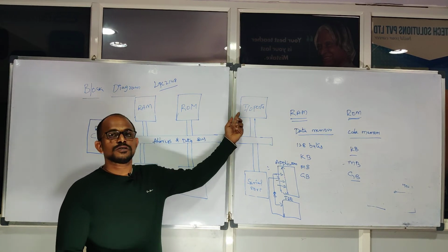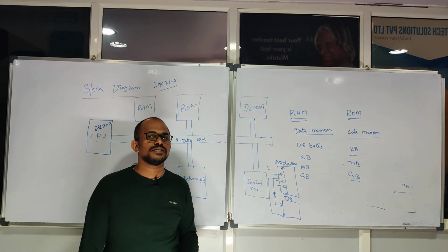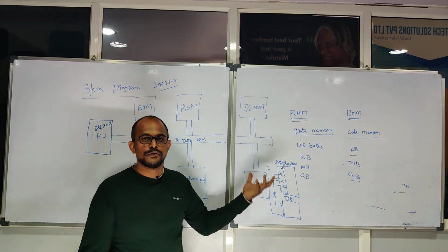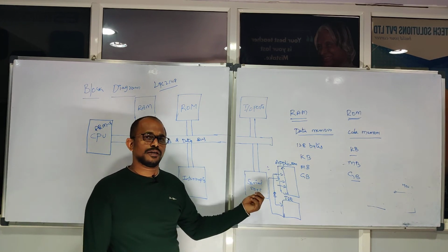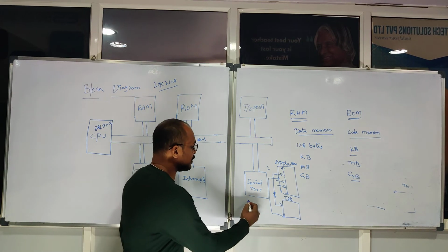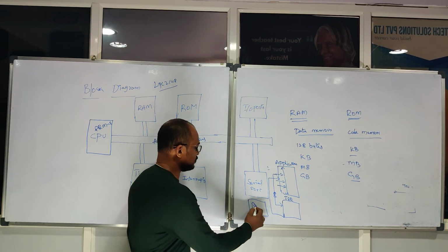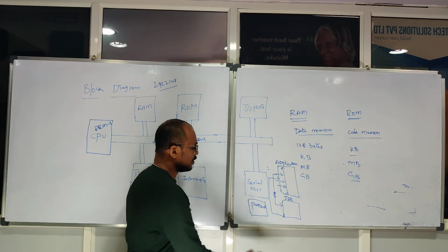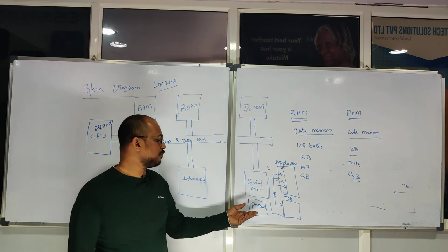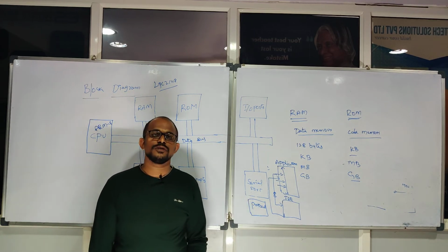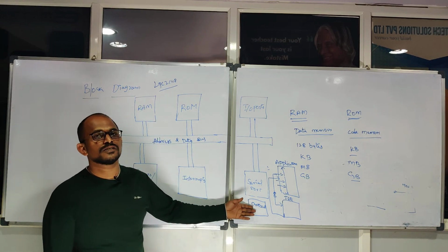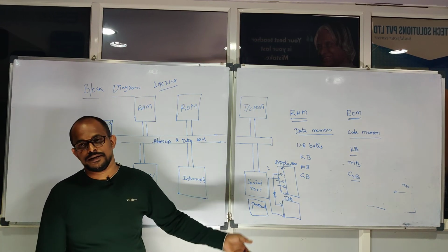Whereas IO ports are used to connect external peripherals directly without knowing any rules and regulations, whenever you deal with the serial port, you must learn the concept of protocol. Without knowing protocol, it is not possible to use the serial port. A simple definition of protocol is a set of rules and regulations. Without following them, your device is not giving data or taking data.